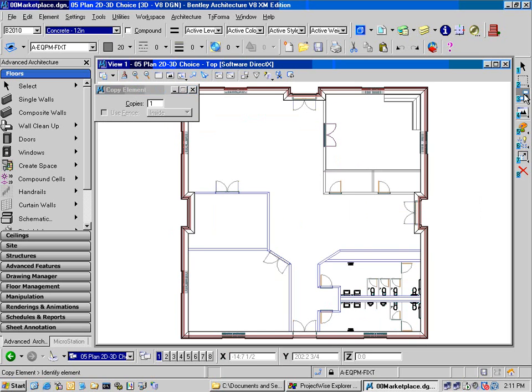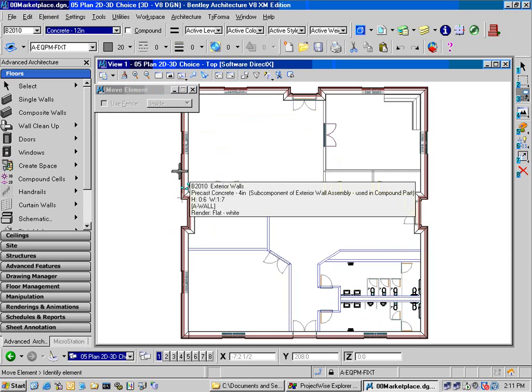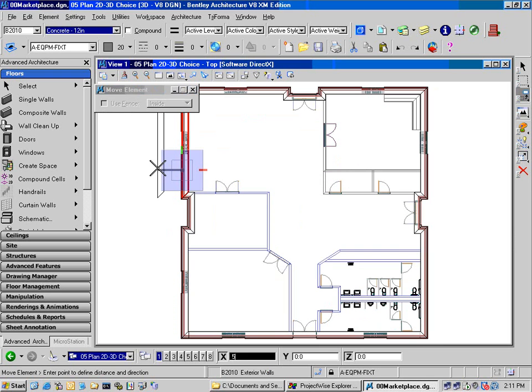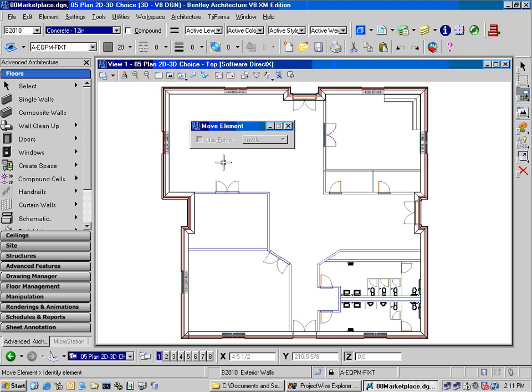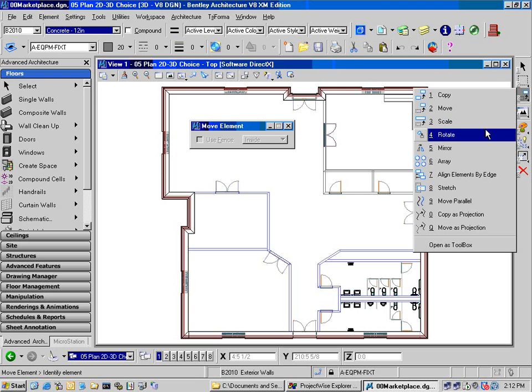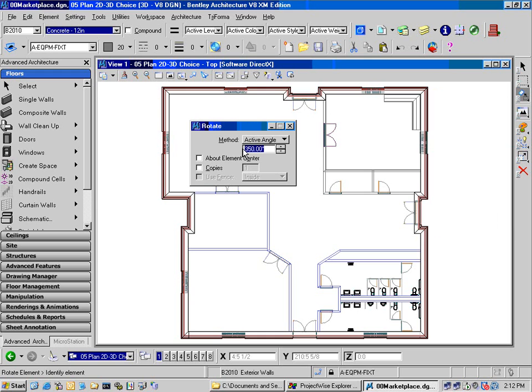And because we've built a relationship into our wall, for example, I wanted to take that wall, move it out, say 5 feet. That's got to do with the locks. Turn our graphic group lock on now, and move it out 5 feet. See, I can control the whole model that way. That's a compound wall assembly. That means it's got some exterior work, maybe some brick on the facade. You can even do things like perhaps even rotate this around, say 10 degrees here. So I'll pick that wall and pick that corner right there. This will clean this up very nicely. I go back to the 3D model.